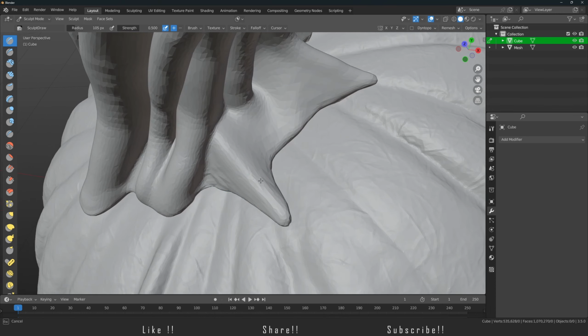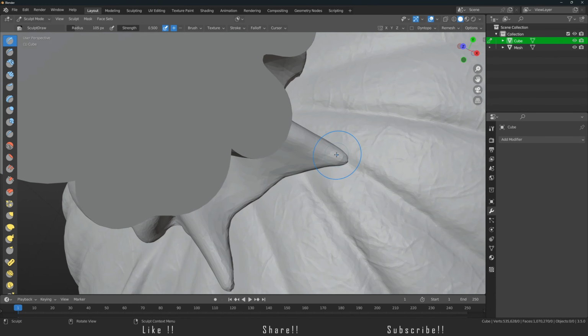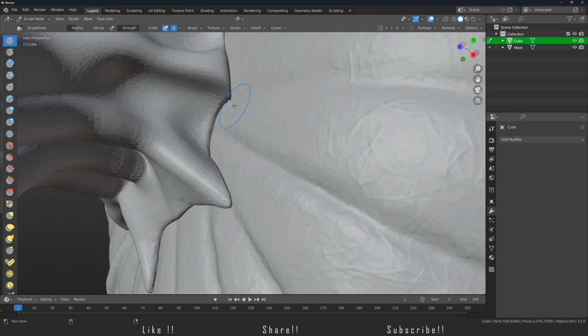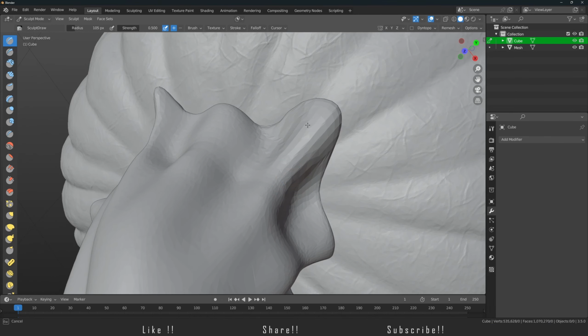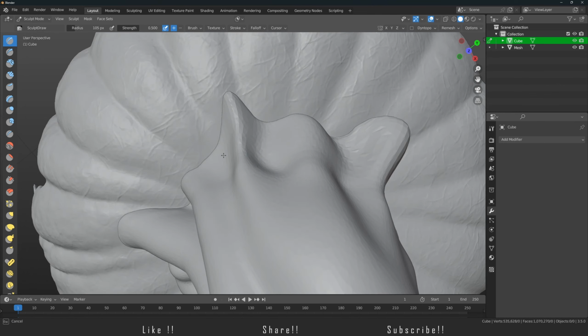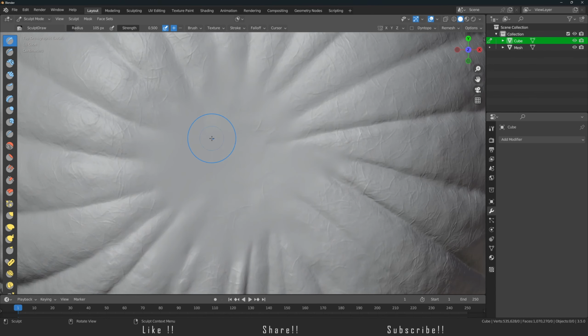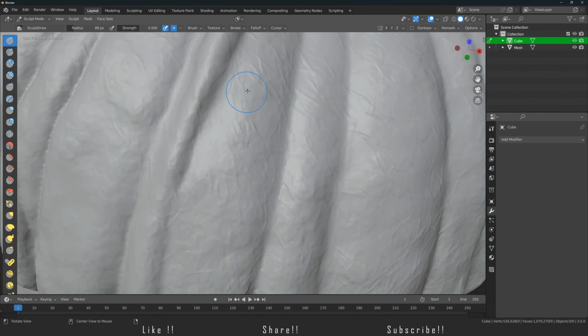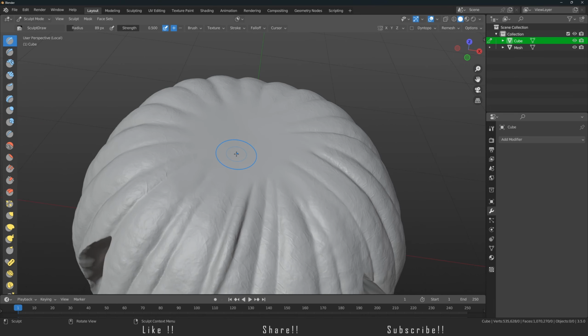The reason that I'm smoothing it out is you don't want any weird area like this, because in the end when you print out the keys, they're not going to get connected if the area is not as smooth as you can make it. So you need to make sure that you create these areas as smooth as you possibly can, and they're just going to get connected.